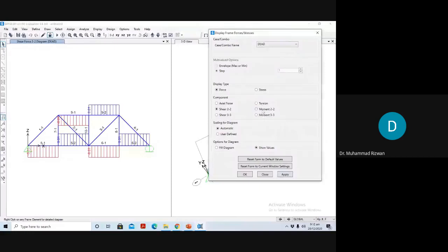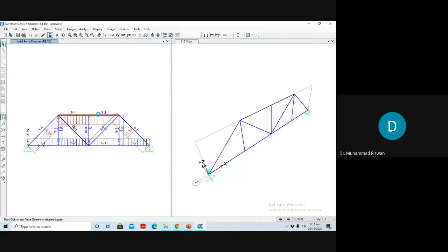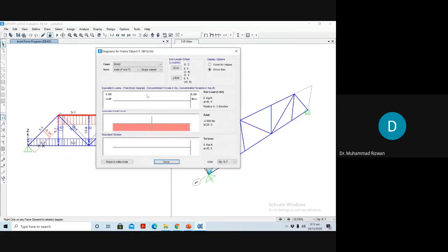moment 3 will be there, shear will be there, okay. See, there will be no moment in these members, okay. This is M33. This is very small, 0.2, okay. Because, you can see only axial load, the predominant loading is actually those axial loadings, as you can see here. This is one way of visualizing the axial or the shear or the bending or the displaced position.